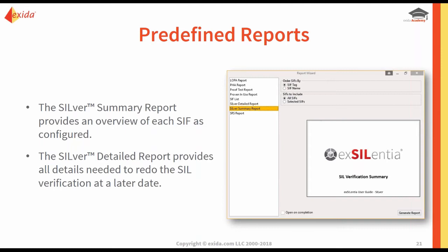So for any piece of equipment that you choose out of the SERH, we have an associated proof test coverage, and that proof test coverage comes with a specific procedure. All of that can be generated into a report where you can have the proof test for your entire safety instrumented system in one report. And if you have SILstat, you can also import that into SILstat, so you can essentially take a tablet out into the plant and record your proof test right into the tool. And so that's pretty cool.